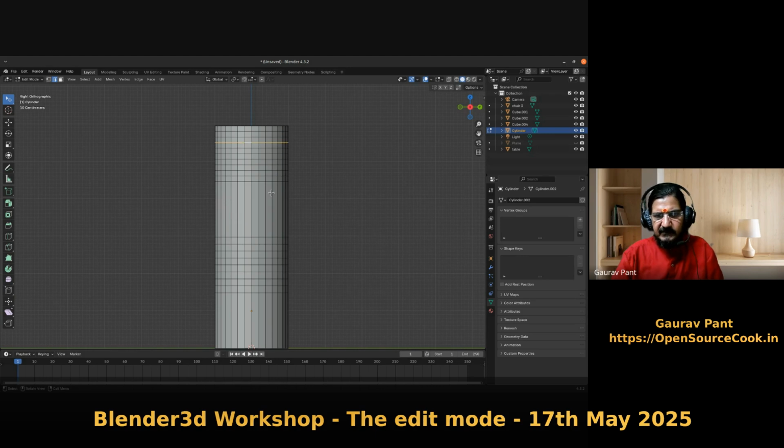Now here we are going to see one interesting aspect that's called proportional editing. You will notice this button over here. This is called proportional editing. The shortcut is, I think, O. Fine. So if you press O, proportional editing will be turned on and off.